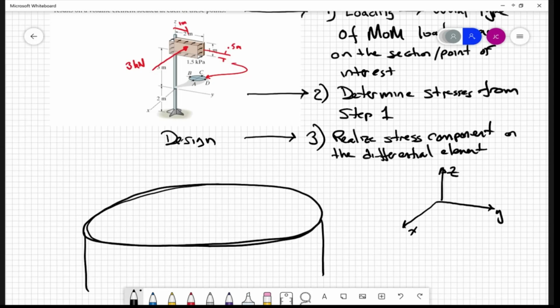That's right. So the 3 kilonewton force acts on this 1 meter torque arm and is going to produce a torque around the z-axis. So what is that going to do on this face? It's going to produce a torque that goes like this on that surface as I've drawn it, right? I know technically I probably should draw the opposite surface on here, but this is as it would directly act on that surface. And that's the direction it would act. And this is going to have a value of 3 kilonewton meters, because its moment arm is 1 meter.